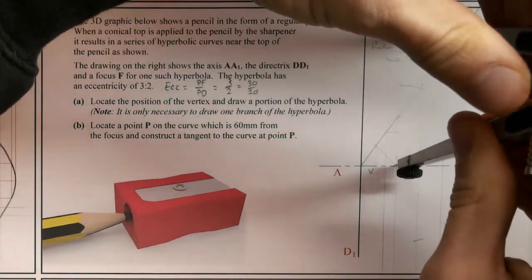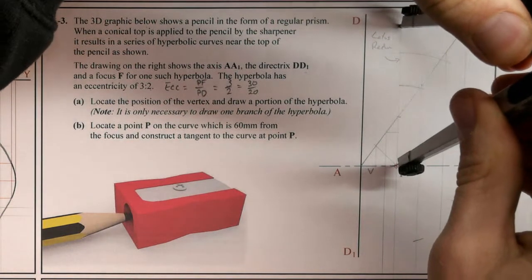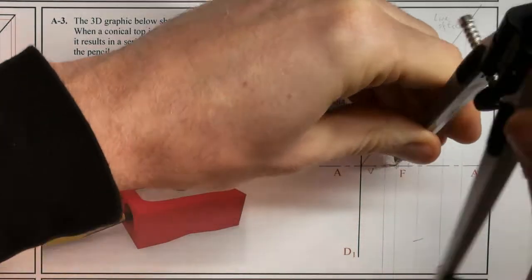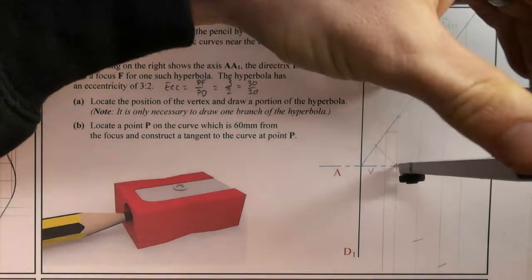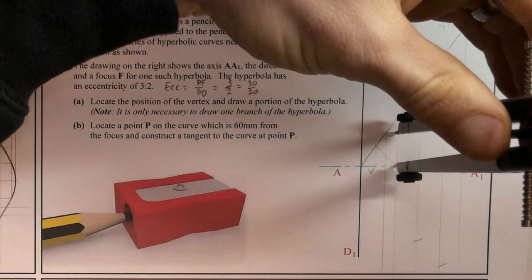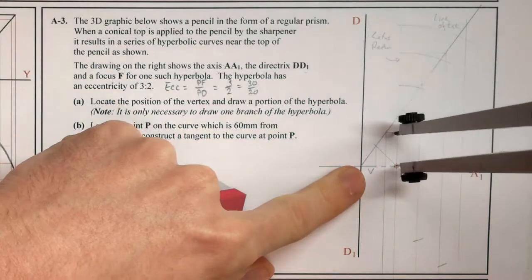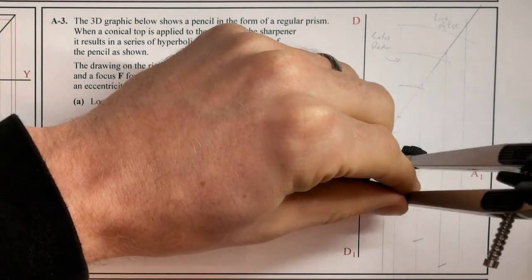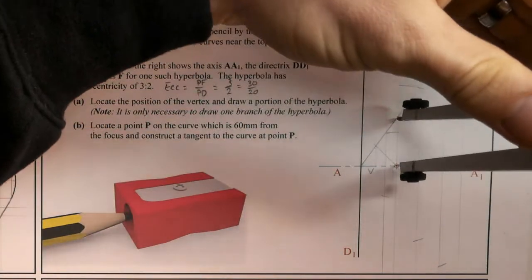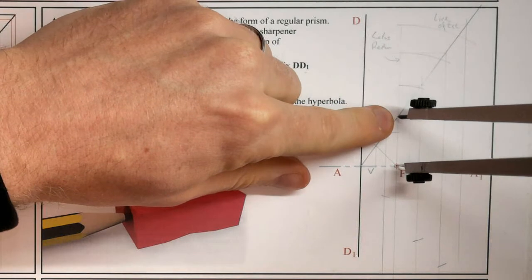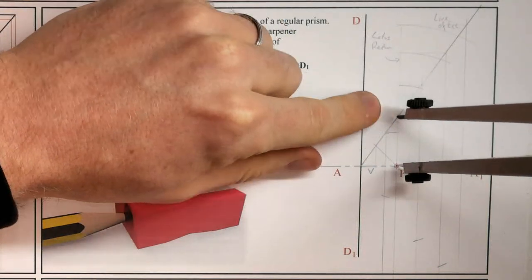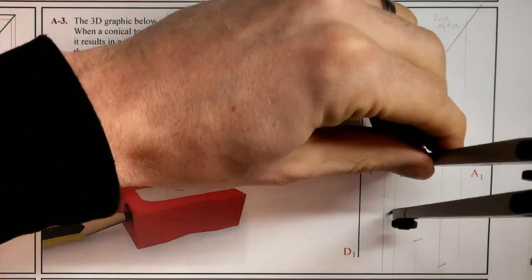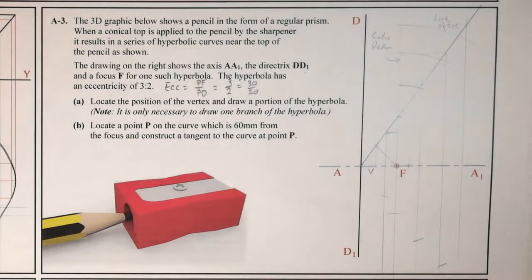And finally, it's gone below where I need it to be. And then lastly, I'll do my point inside the curve, rotate it down, and locate that here. And don't forget, as I said at the start, this is a point where my latus rectum intersects my line of eccentricity. That is also a point, so I can actually show that down here too.